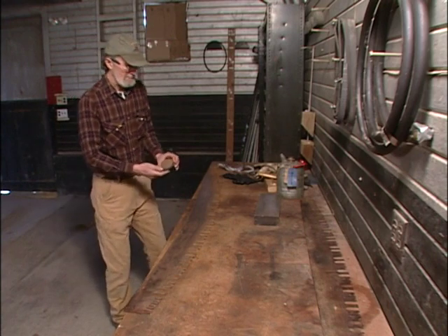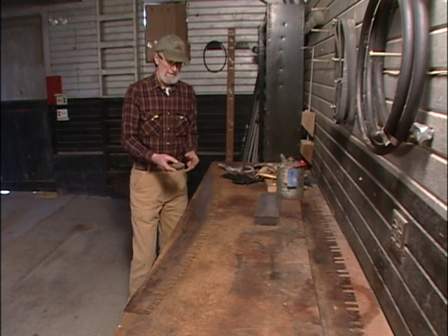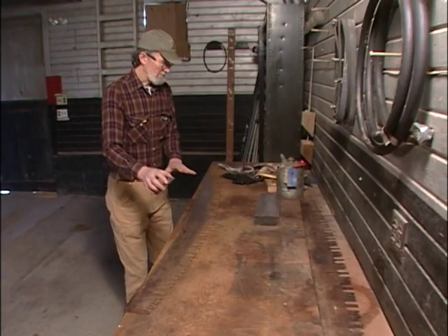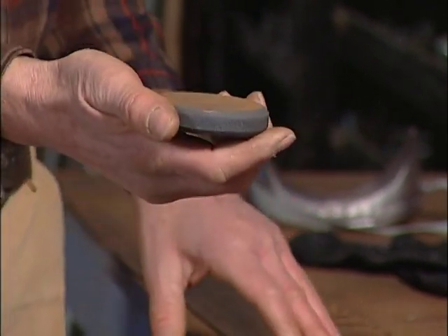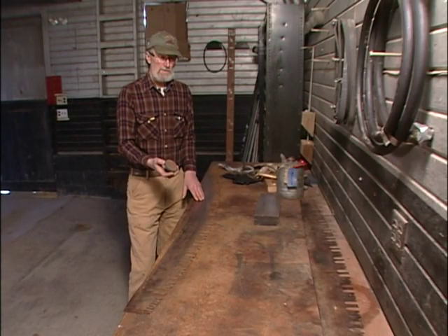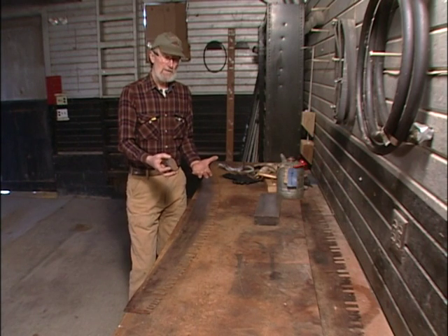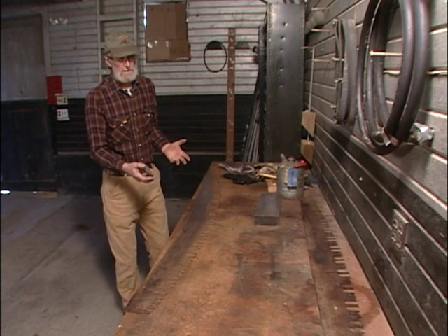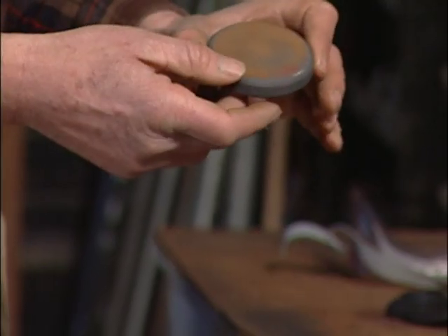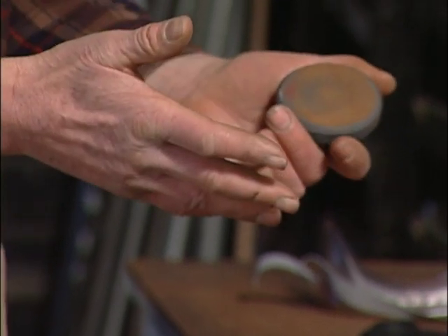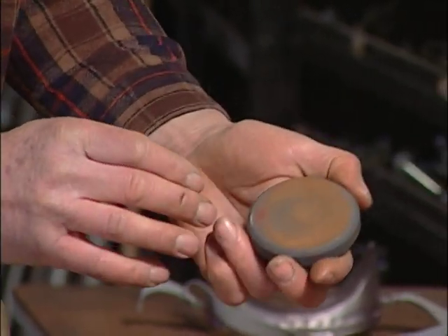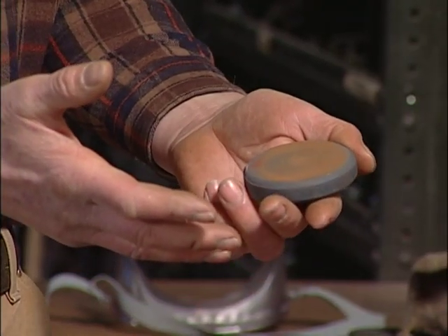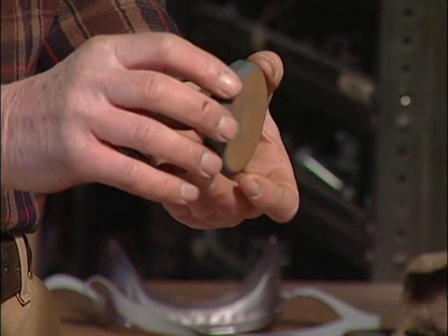Normally, what I end up doing for cleaning is that I use an axe stone, which is just a round stone, and I'll liberally douse the saw with some sort of a solvent. Normally, I'll use a petroleum solvent because if you have pitch on the saw, the petroleum solvent will cut the pitch and make it easier to do your cleaning. The reason for using a fluid at all is that if you don't, the pores in the stone will end up plugging up pretty quickly, and your stone won't cut anymore.